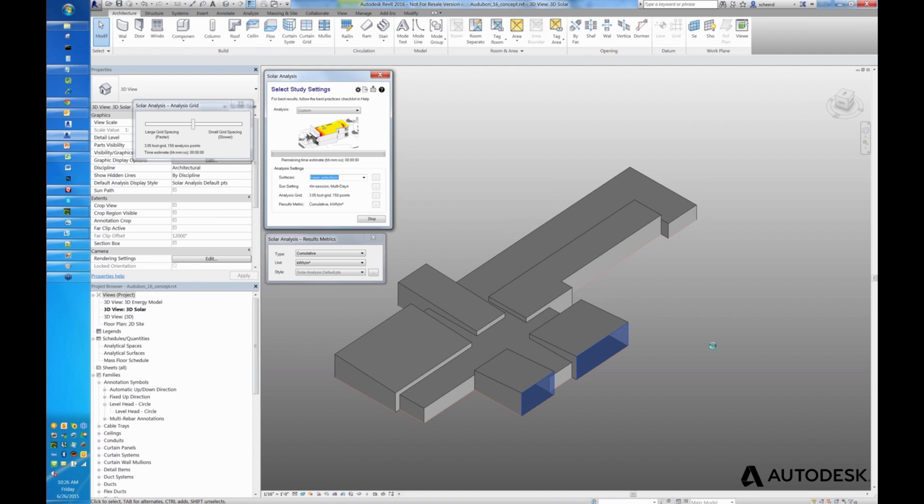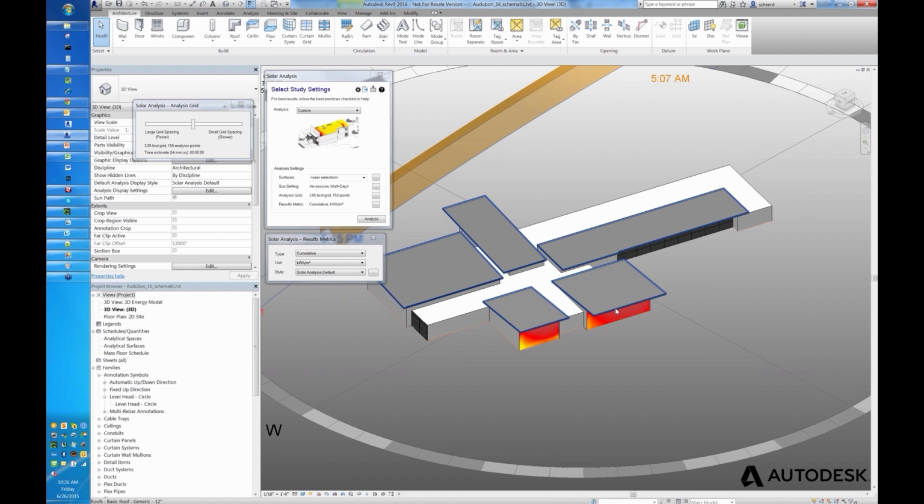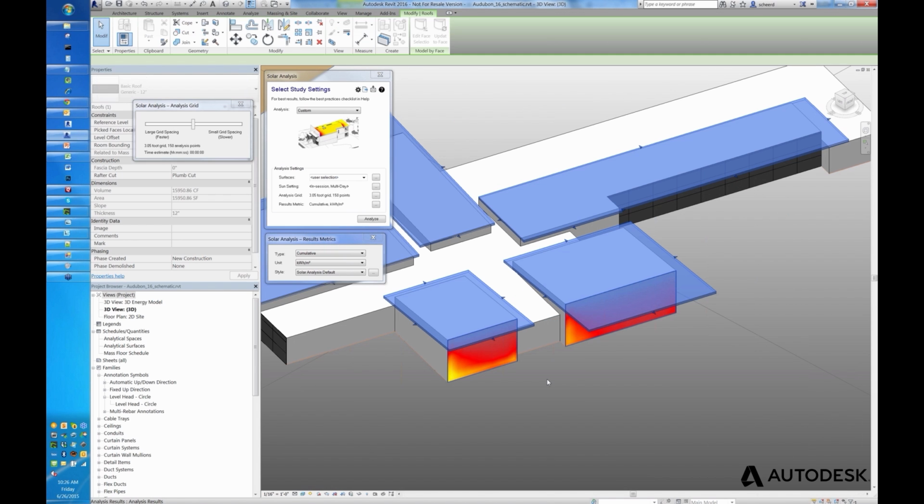So if I want to get into a shading design with more detailed geometry, I can start to add some detailed modeling components to it. And I've got a model that I've taken a couple steps to add, basically turn mass services into roof services, where I can start to very easily vary the roof overhangs and then regenerate the analysis results.